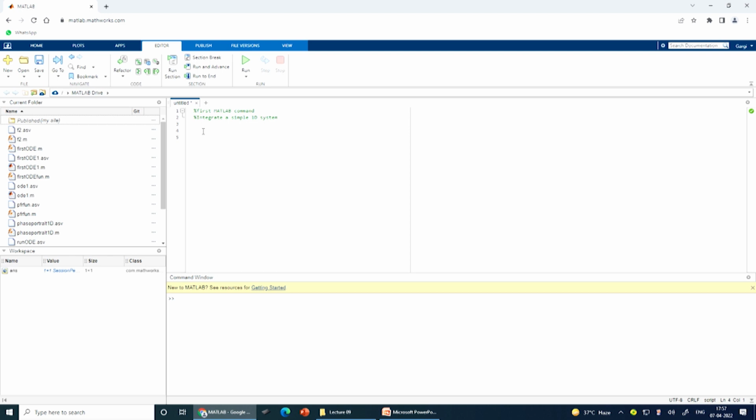So for integrating the system, first you need to tell MATLAB that you are dealing with a system. We'll do that by the syms command. And we want to tell MATLAB that our system is y(t), y is a variable, it's varying with time. And then we will inform MATLAB that this is an ODE, an ordinary differential equation that we are dealing with.